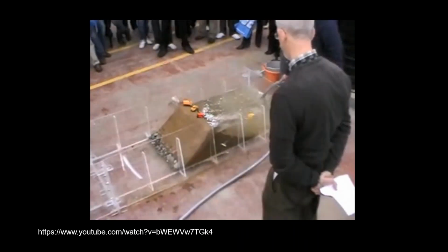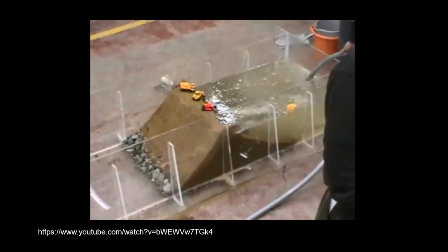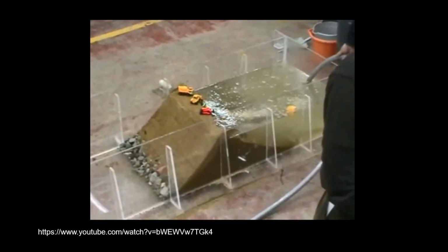Now, for some dams that are flood control dams, they could be dry most of the time, and only during flood events will the reservoir fill. For other dams that might be multi-purpose, you might have a normal pool for recreation or for water supply, and also a flood component. So there might be a part of the dam that is saturated. Now this is the same video, but it shows later on, you can see the dark zone.